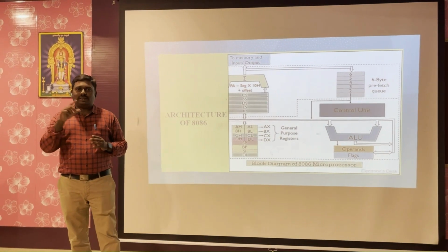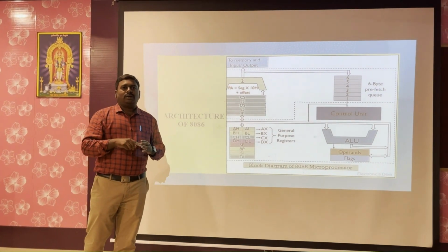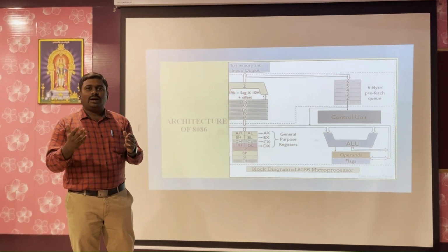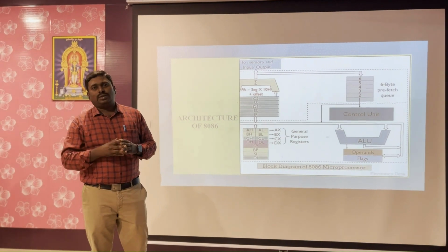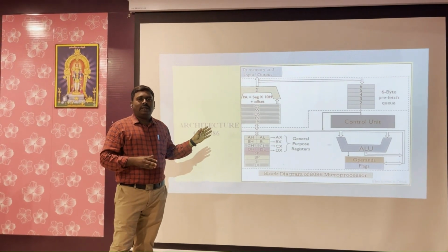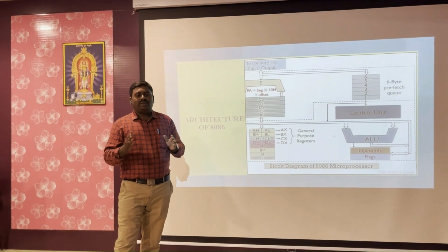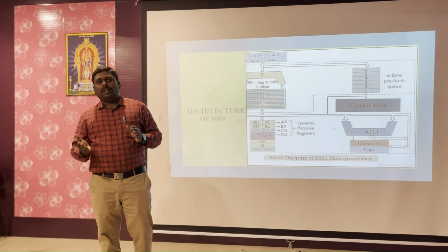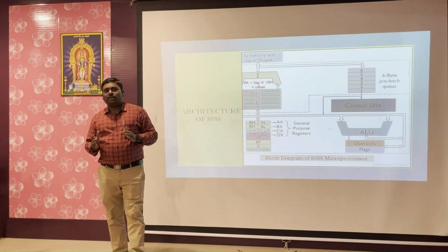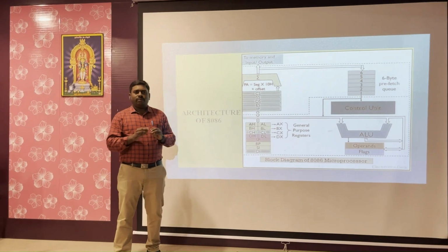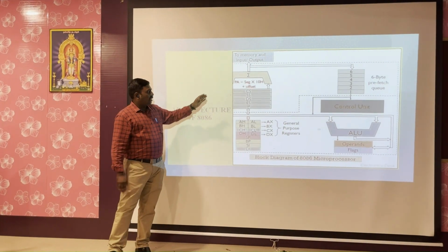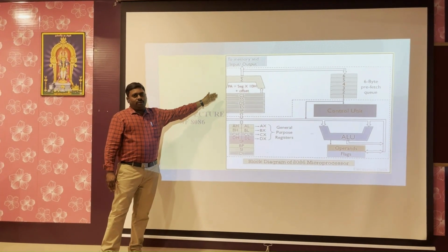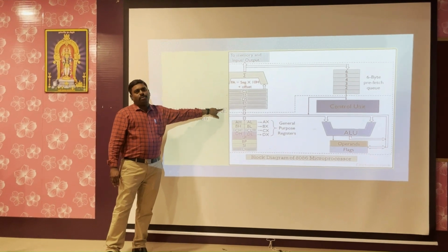So it is very easy for us to search in chapter 1. Without separating these chapters, it is very tough to identify or find particular topics. That's why the microprocessor has 4 segment registers, which easily fetch the data for the process. In a single memory it is very difficult to access. So that's why we make it into segments like code segment, stack segment, data segment and extra segment. Followed with the segment registers, we have the instruction pointer.